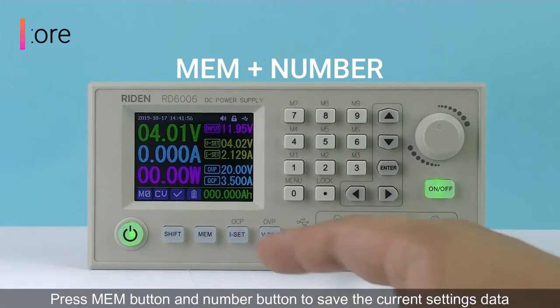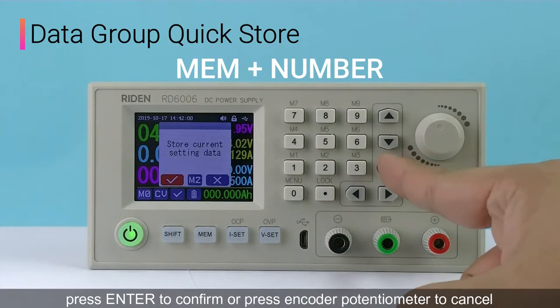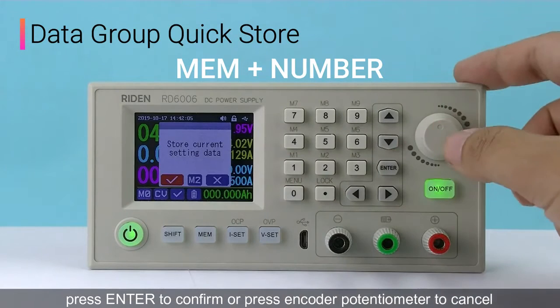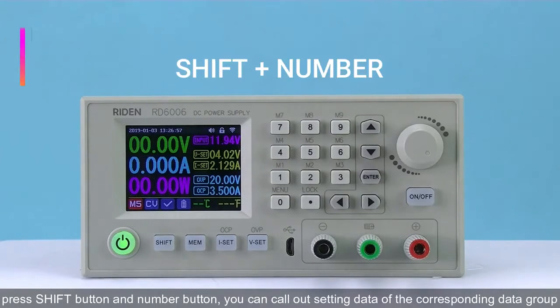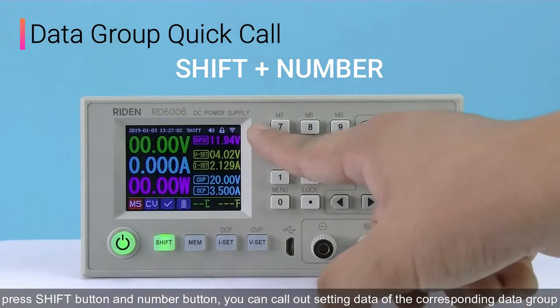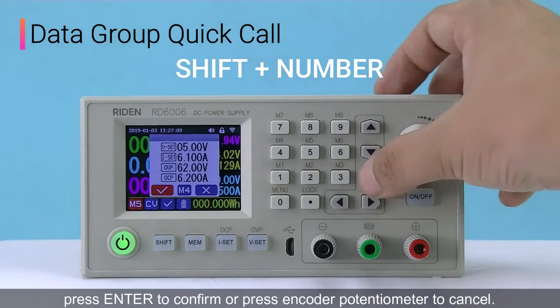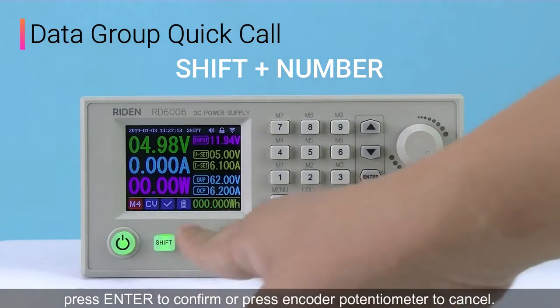Press the memory button and a number button to save the current setting data to the data group. Press Enter to confirm or press the encoder potentiometer to cancel. Press the Shift button and the number button, and you can call out the setting data of the corresponding data group. Press Enter to confirm or press the encoder potentiometer to cancel.